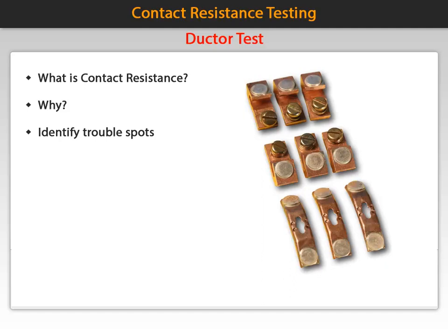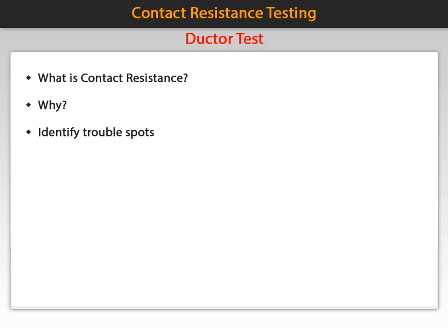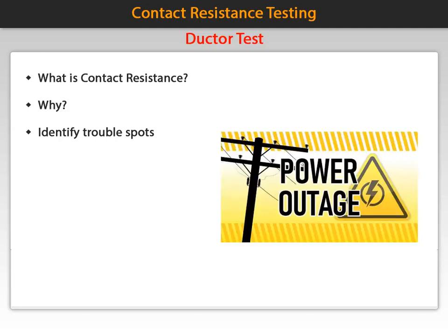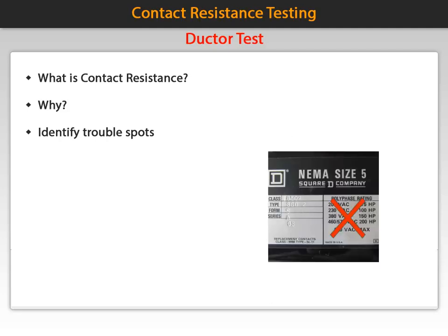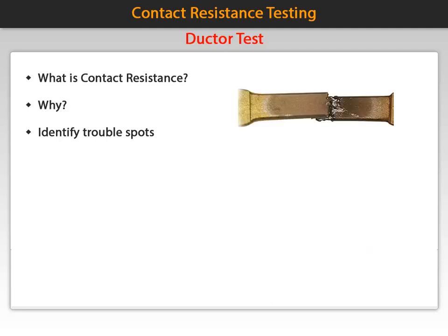Increase in contact resistance can cause a high voltage drop in the system which needs to be controlled. Contact corrosion leads to power loss, heat generation, loss of contactor capacity, and failure to interrupt current when required. Let's spend a little more time on this subject.